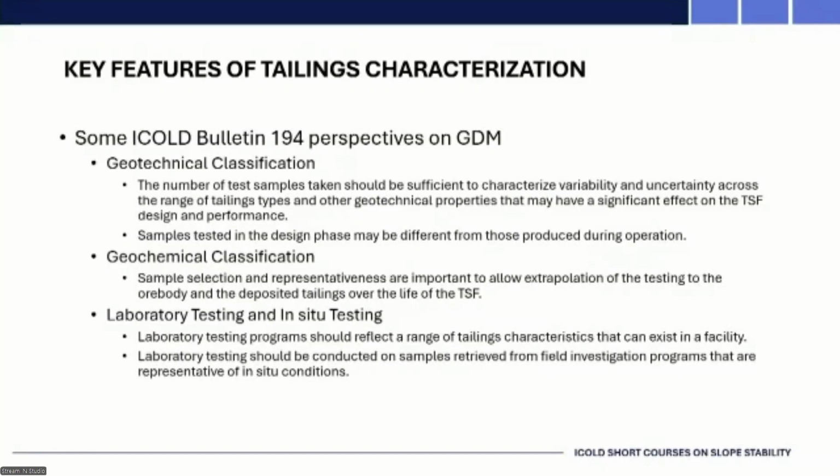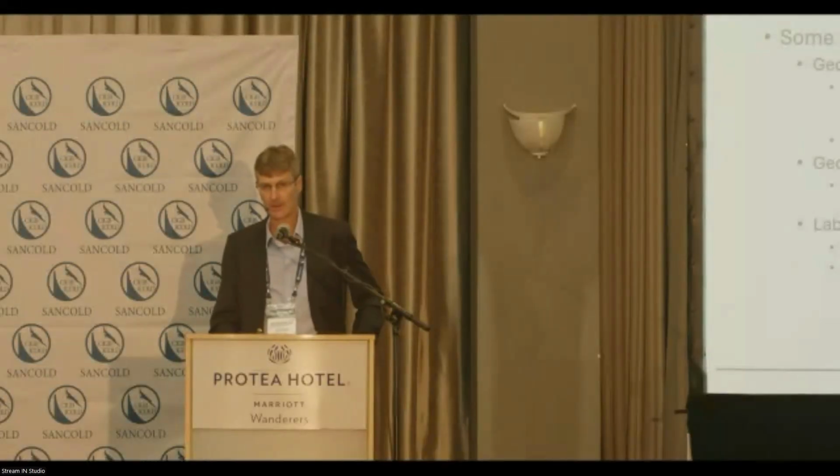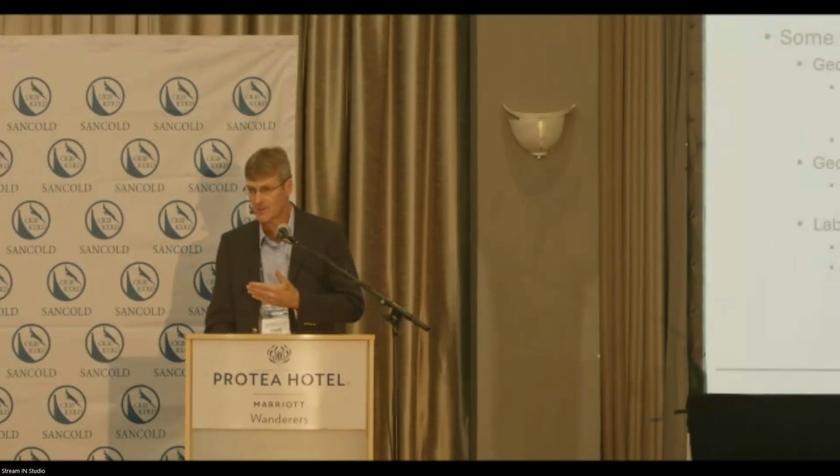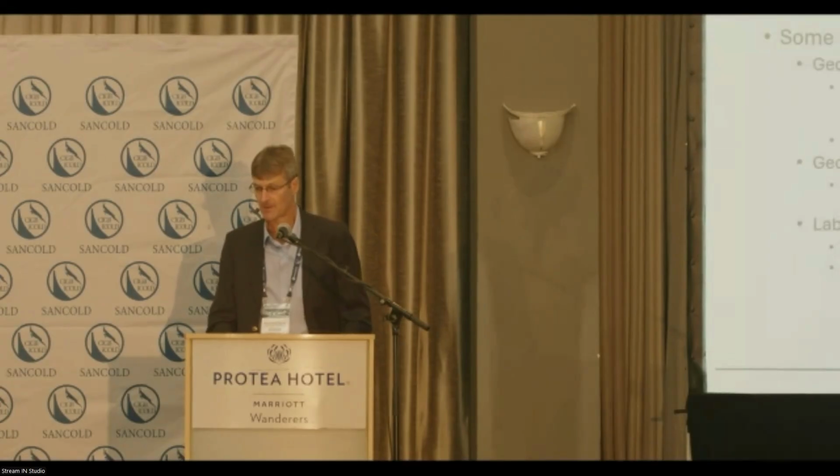And you've got to make sure that you cover the variability of the site. Foundations can be quite variable, as you know, in a valley, as opposed to the areas you've got, whether it's transported soils or residual soils, and obviously there's faulting. And you need to understand how that all affects your performance of your facility.